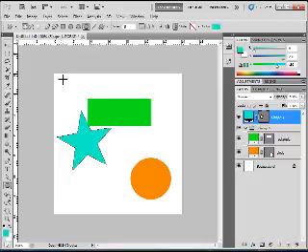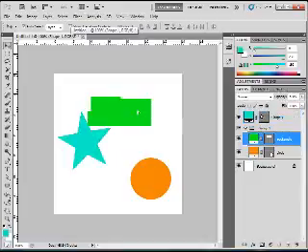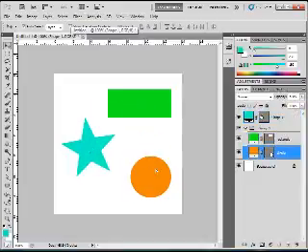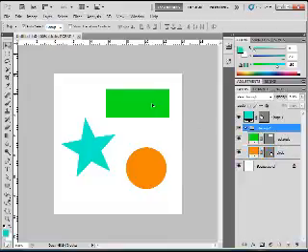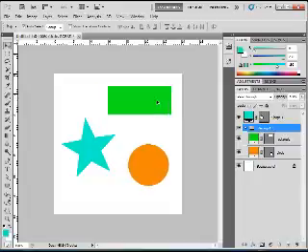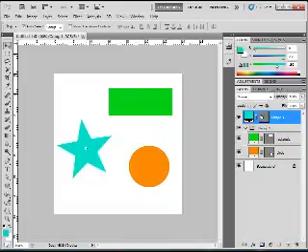and you can see now, select the move tool again. I'm going to press V on the keyboard, and when we've got the layers option selected still, we can still select the individual shapes on the screen, but by going back to the options here and selecting group, you'll notice in the group we've got our rectangle and circle. If now we select one of the shapes on the screen, we can move all the shapes or the items in the group, which is quite a cool feature. But if the items are ungrouped, it still allows you to move separate shapes or single items.